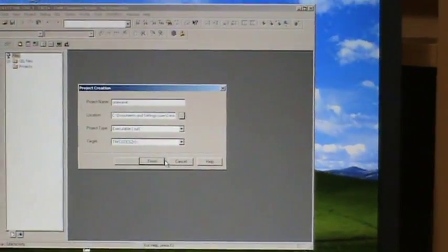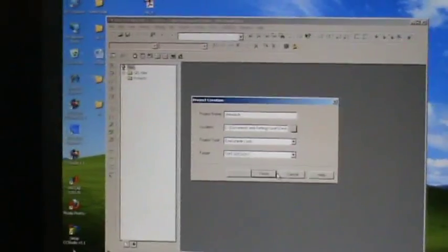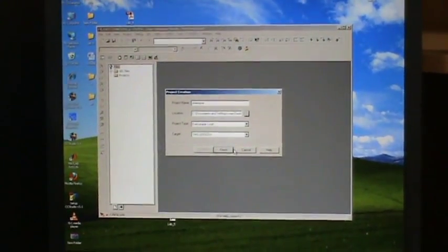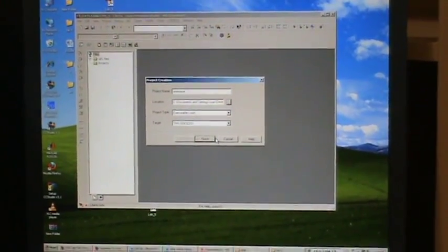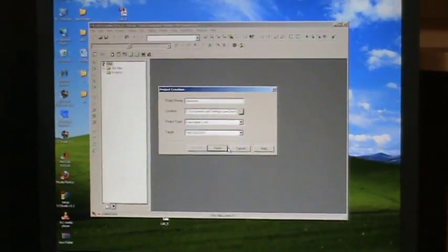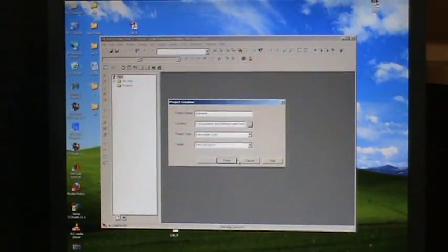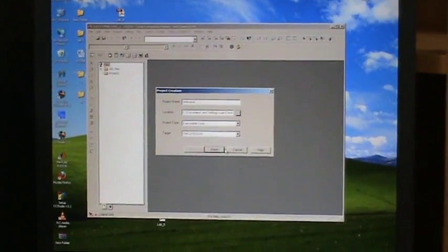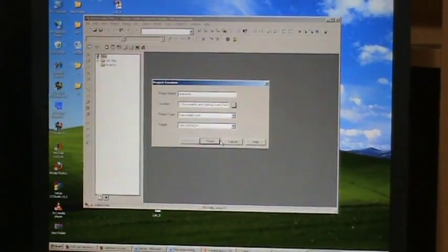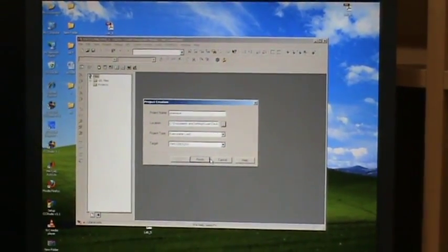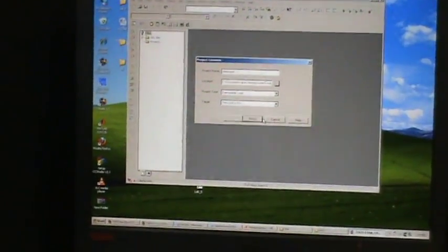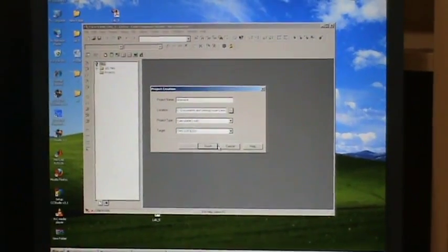I shall add some additional files to make the DSK kit work. Include the same files in my C code, and explain some details regarding the files: sampling rate definitions, codec open, writing into codec, reading from codec, etc. I shall add some additional lines to make the DSK kit work, like sampling rate control, how to open the codec, writing samples to the codec, why 2 times, why it's less than 2 and more than 2, and close codec. These are some basic things related to the codec that I'll discuss.